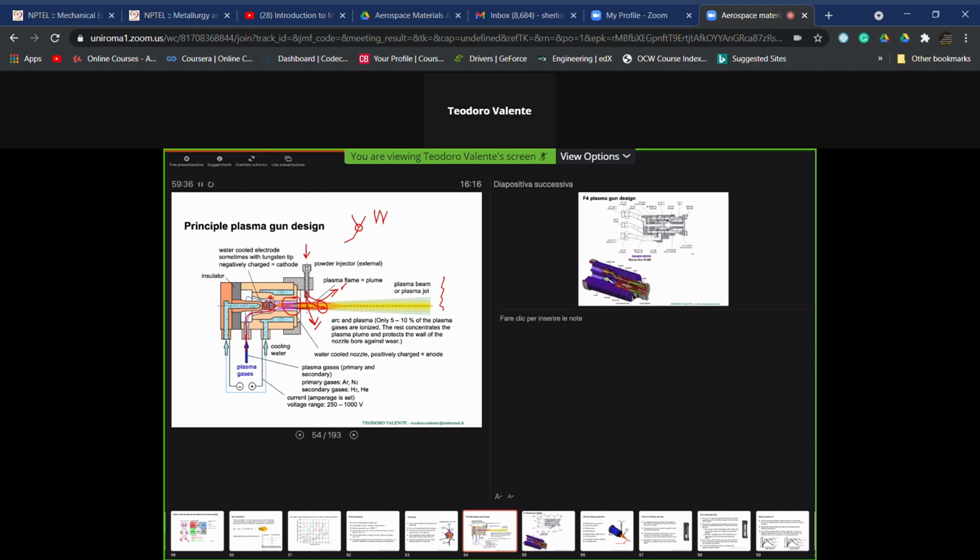It must be a metallic part. Which kind of materials, up to you, could be used in order to have what is very important here, a very high cooling efficiency? Because you see, this is the part of the plasma formation which is in direct contact with the anode. We need to use materials with a very high thermal, or if you want, electrical, that's the same, conductivity. And so this selection is copper.